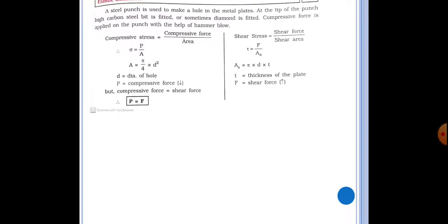The equation for strain x is equal to sigma x upon E minus sigma y upon mE minus sigma z upon mE, right? Epsilon y is sigma y upon E minus sigma z upon mE minus sigma x upon mE. Strain z is equal to sigma z upon E minus sigma x upon mE minus sigma y upon mE. These three equations are most important for us, and we have to memorize them in any case or any condition.